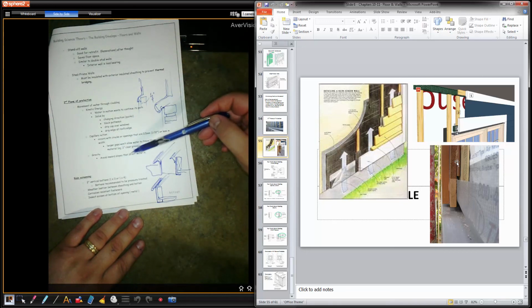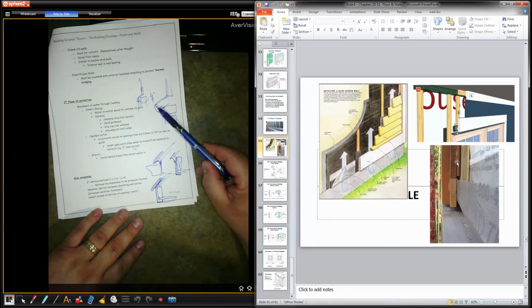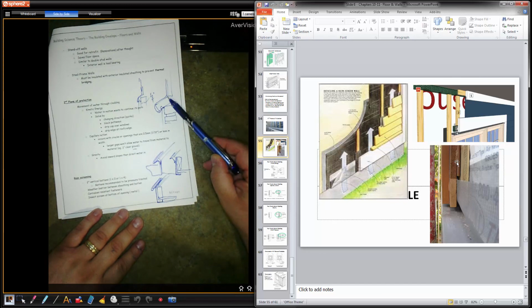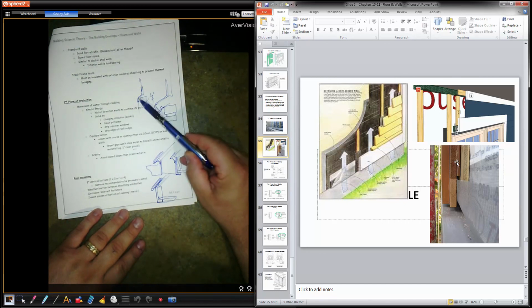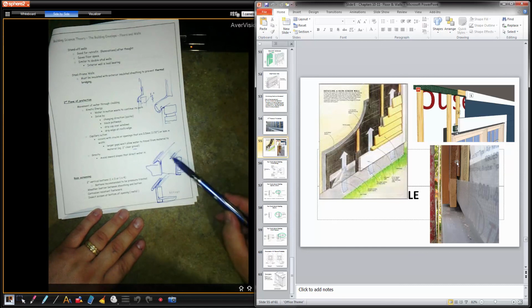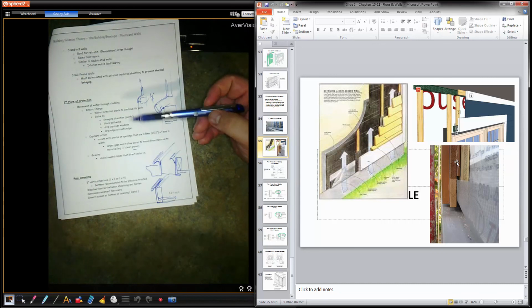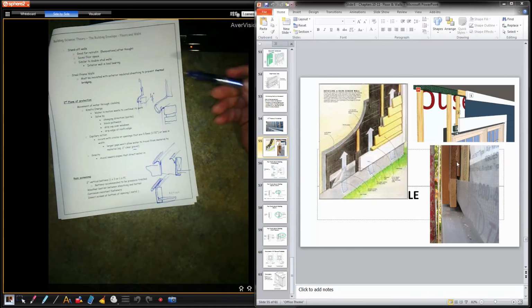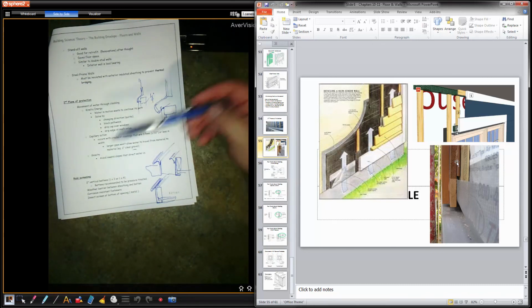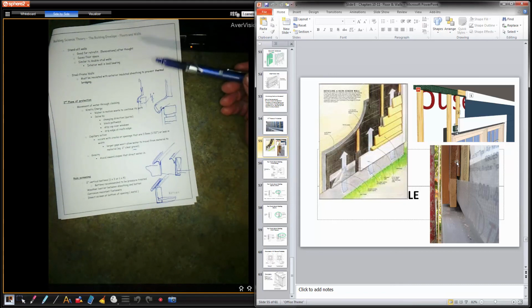Avoid inward slopes that direct water in. So you see how the sill of the window is out. The angle on the drip cap is out. Naturally, the roof is already sloped, so we have that working for us. Make sure things are angling outwards to make sure water travels down, driven by the force of gravity.